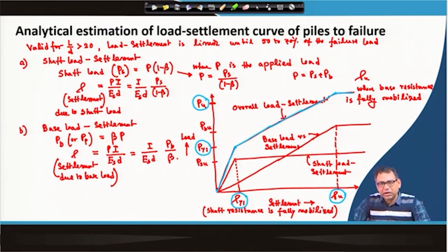That will not create any effect on the pile material settlement, because at that time the soil settlement is going on. As I mentioned, when the soil settlement stops, then the pile material settlement will start. So, the tip resistance during the friction resistance mobilization will not create any effect on the pile material settlement.